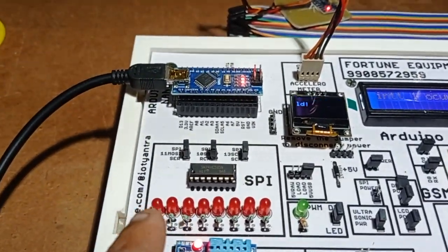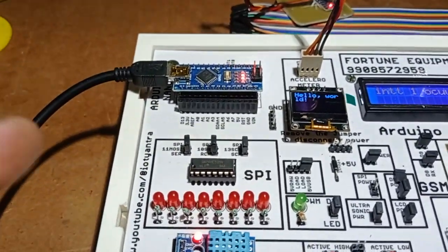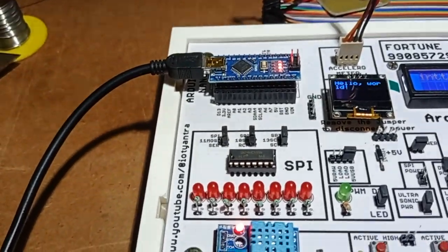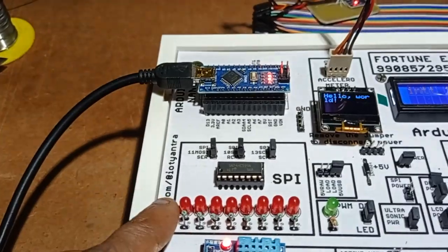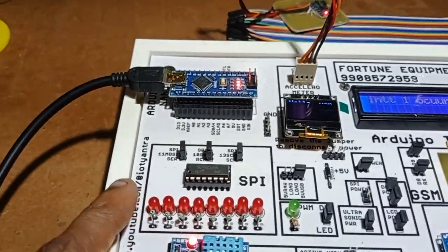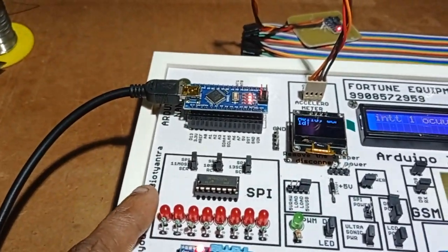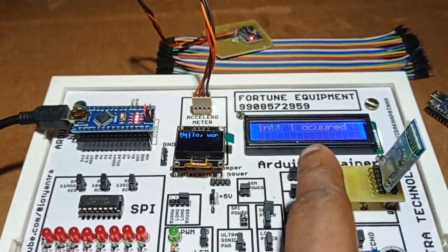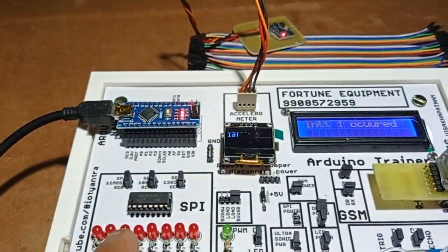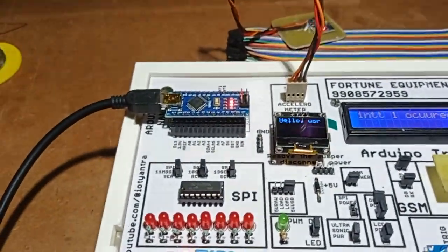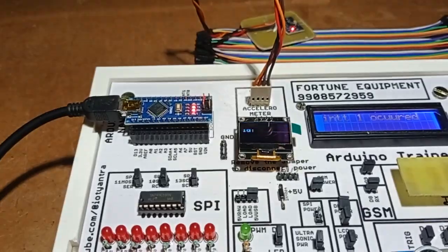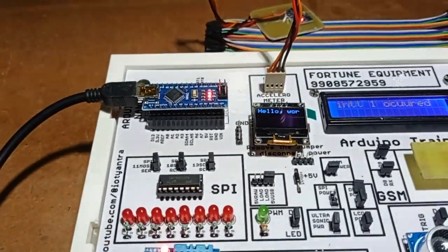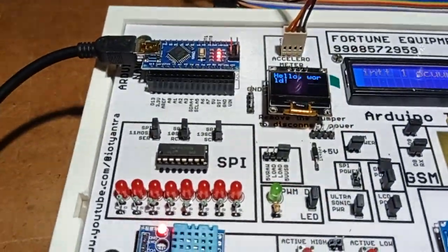In SPI, you have the same clock line, but two different data lines. One from processor to slave, another from slave to processor. And there is one more pin, which is slave select. That particular pin selects a particular slave, and there is no address in the case of SPI, whereas in I2C there are fixed addresses for slaves. It is only the master which addresses a particular slave by setting a particular pin either high or low, and it starts communication with that. There is no address concept here.